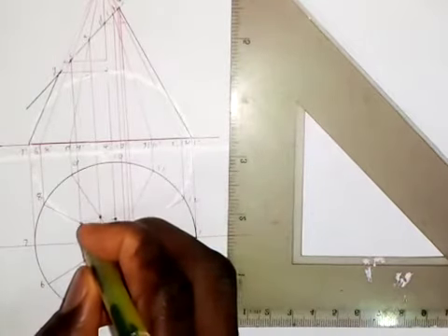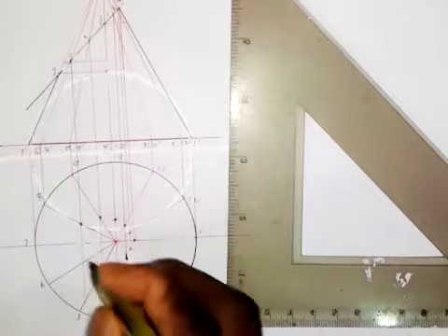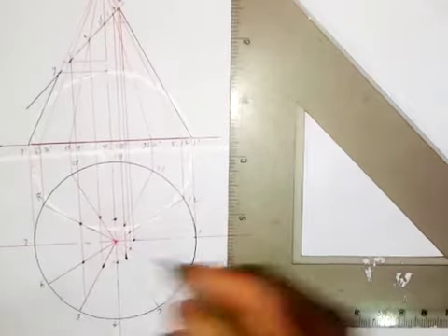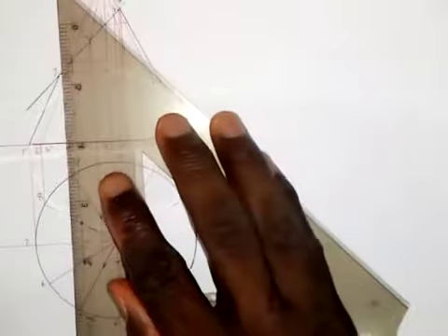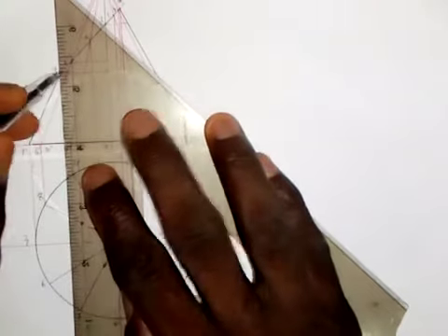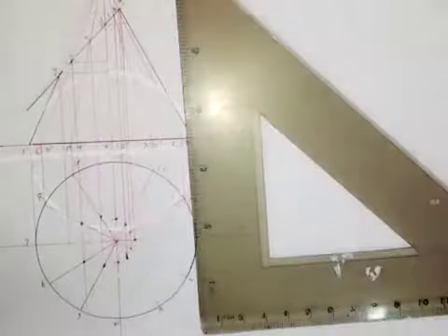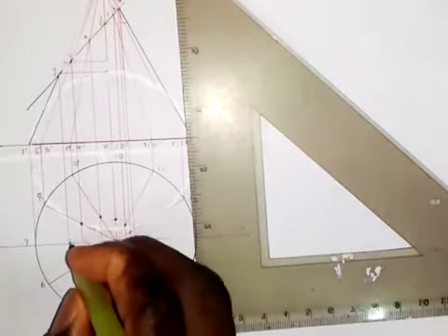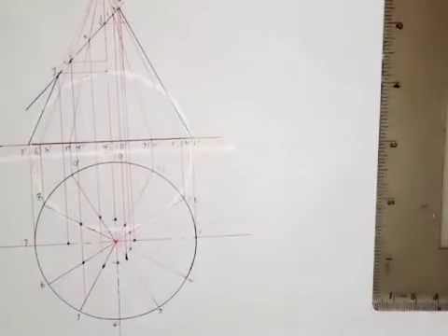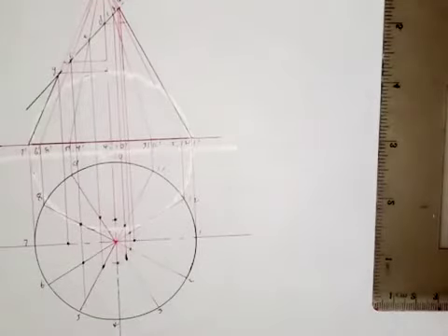Touches 8 at this point. This contains 6 and 8, and touches 6 at this point. So the last one is point G, where we have point 7. Draw a vertical line so it touches 7 at this point. All these points will be joined together with the use of a French curve. I will join it and come back and show you the next thing to do.